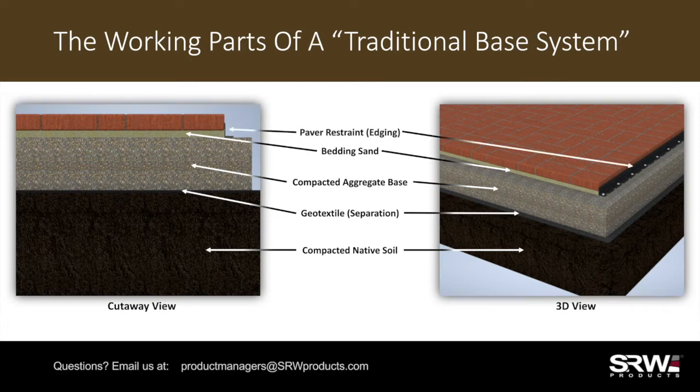The paver restraints or edging, which is installed along the sides of the pavers, help prevent movement from any of the pavers and breaking interlock. The concrete pavers themselves, and finally the jointing sand to provide the interlock that keeps everything from moving.